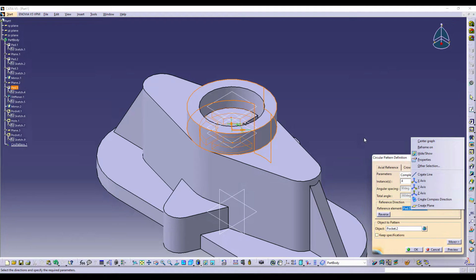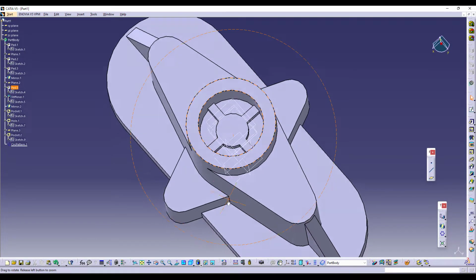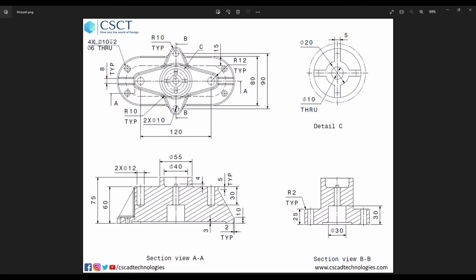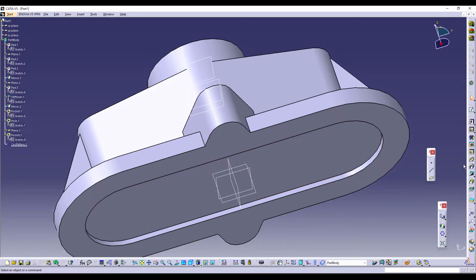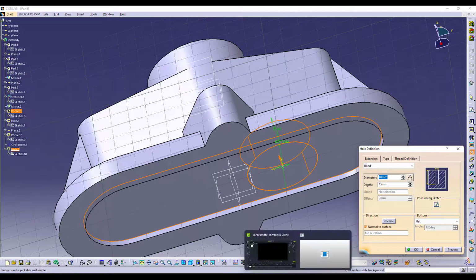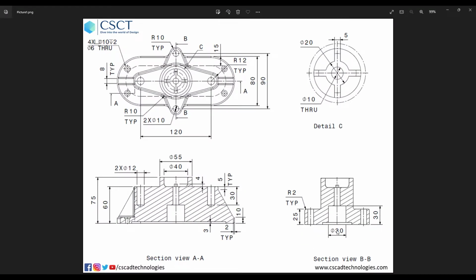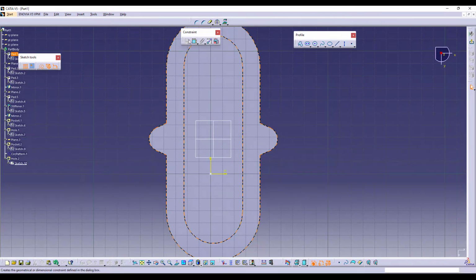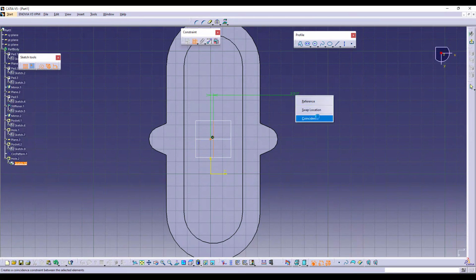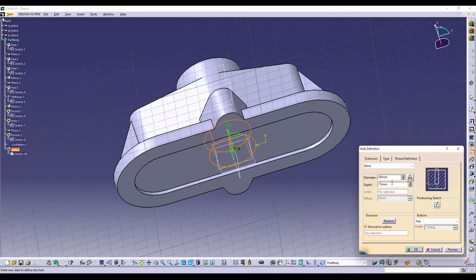We can use Z axis as well. So once I say OK, you can see the slot cuts. These slot cuts are these cuts. Now there are other holes as well. So let's try to take the hole from the bottom, which is drilled at 30 with diameter 30 at the center location. So I can give 0, 0, like how I said earlier, you can coincide at 0, 0. I am trying to do that right now. Coincide at 0, 0.